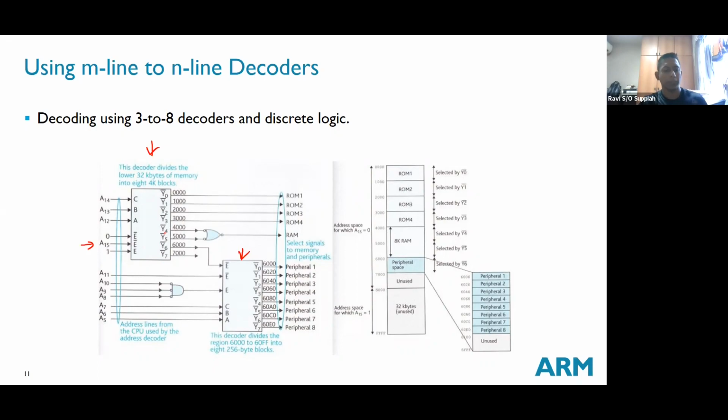Chip select or chip enable or enable. In this decoder here, you have three different enable pins. The E bar means you have to have an active low to activate it, that means a 0 to activate it. The E by itself means a logic high, so a 1 activates it. And this center one, E bar, is also active low.